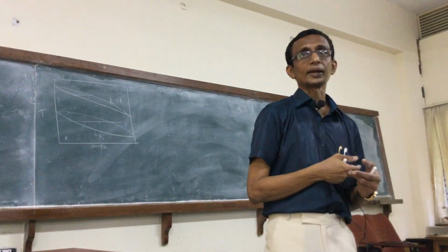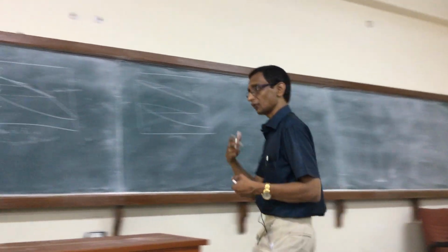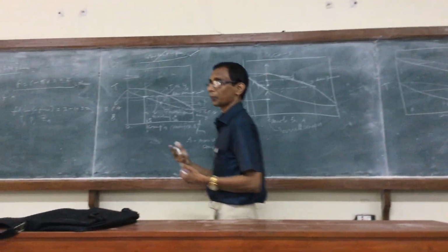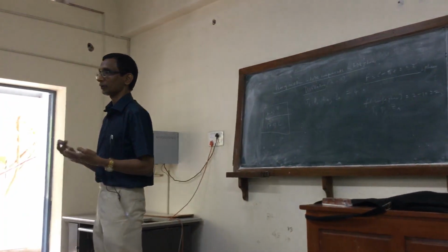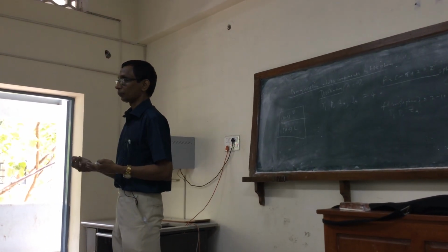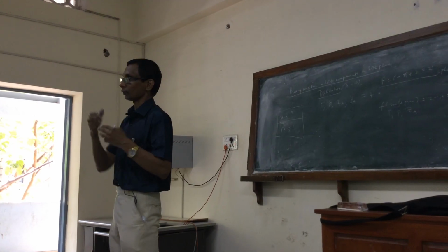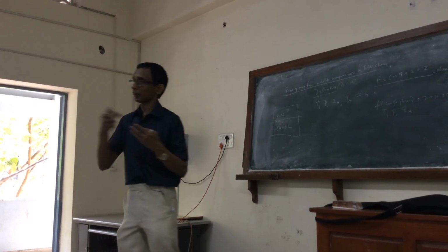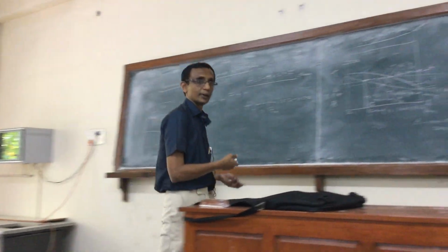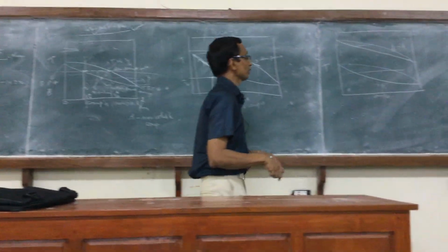What it means is that when we want separation, we want as much difference in composition. That's why we are creating vapor in the first place. And we have 50%, let's say, liquid A and B. So I want to vaporize it. So the vapor maybe will have 63% A, and the liquid will have less of A. That is the whole idea of separation.